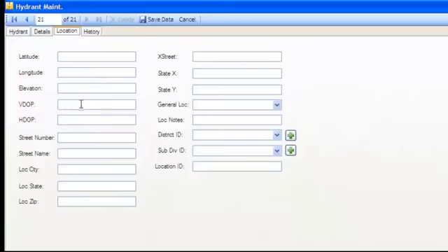In our latitudes here in the United States, we usually see numbers on HDOP of 0.7 to 1.2 or so. But that does depend on your location and your access to clear sky, especially clear southern sky.